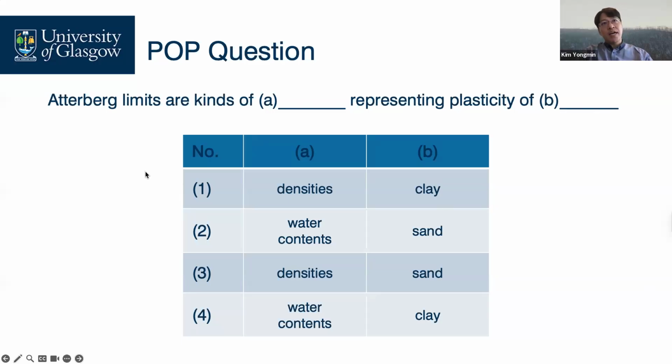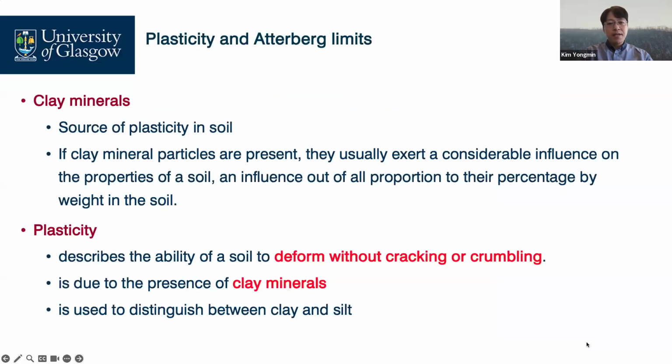Yes, the Atterberg limit is kind of density and representing plasticity of, oh, sorry, kind of water contents and representing plasticity of clay. The mechanical behavior of fine-grained soil is linked to four distinct states: solid, semi-solid, plastic and liquid, in order of increasing water contents.